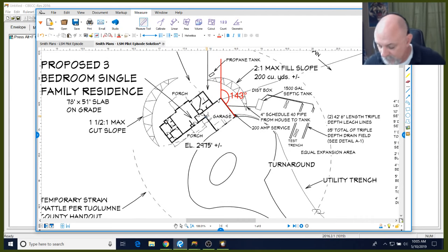So I'm going to start doing my takeoff here. So the front is 143, and it's real easy. We only have 4 cardinal orientations. So 143, and we just add 90 degrees to that. It's going to get all four of our facets or faces of our building. So 143, my left orientation is 233. That's degrees. Add 90 to that. My back orientation is 323 degrees. If I add 90 to that and then subtract 360, it's going to bring me back around to 53 degrees to my right side.